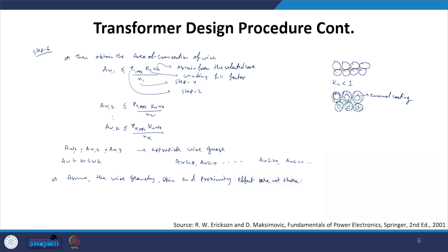That means we have not considered AC winding losses. What we have defined is just I square rho L by A, which is just the losses corresponding to the DC excitation, but generally these transformers are applied with high frequency AC. So accordingly, approximations can be taken and then the required thing can be obtained.